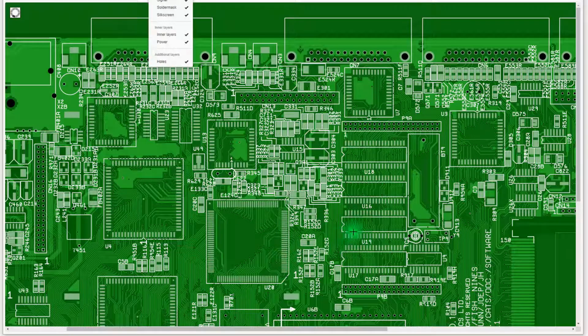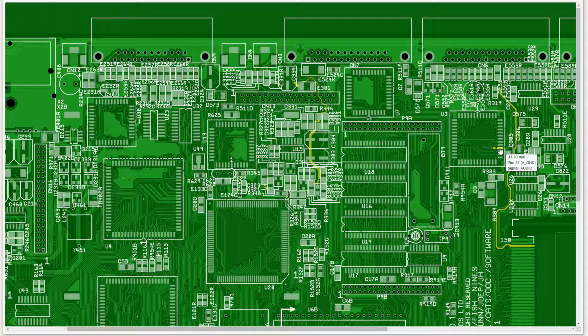The second reason that this drawing is really valuable to me, and we'll talk about this in my documentation, is having an idea where things are on the board, having an idea where I want to probe. I'm going to want to probe these two pins. I'm going to want to probe this pin. I'm going to probe these two pins to make sure the Paula is outputting audio on both channels and to make sure that this ground reference looks to be 0 volts.